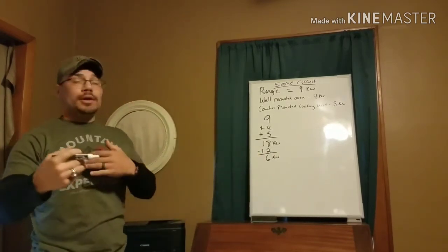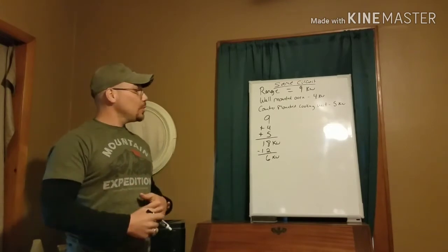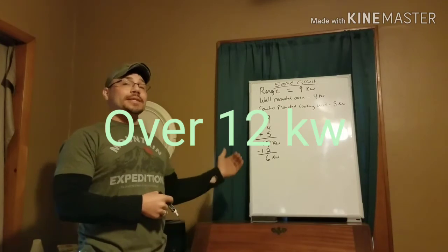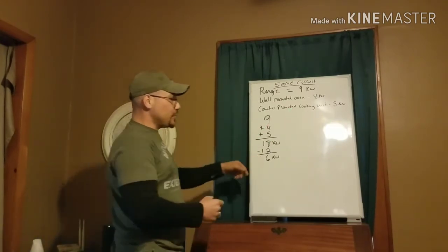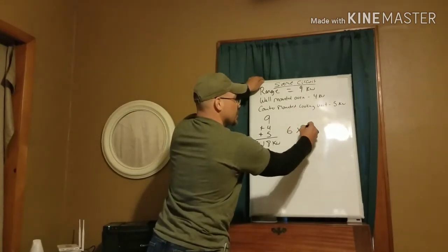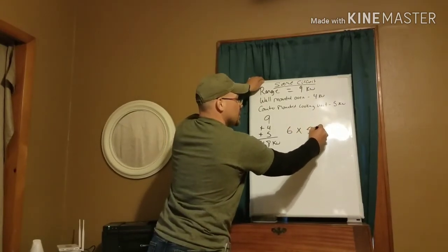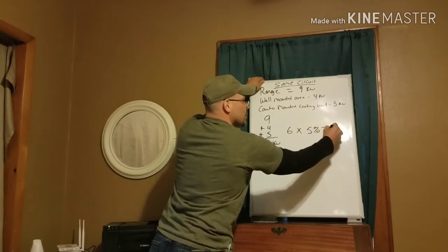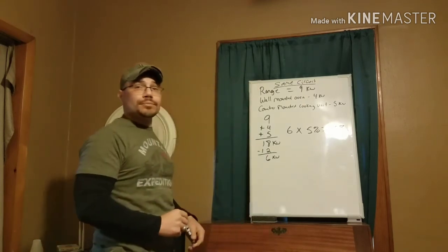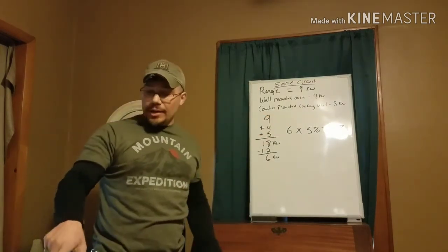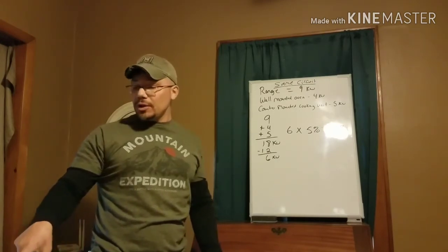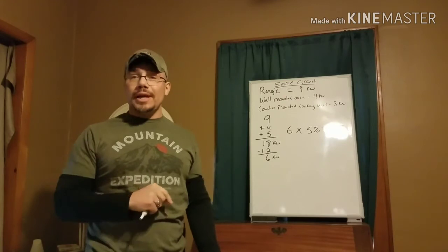Then it says for every 1,000 watts, or every major fraction thereof, we have to take that times our 5% again. So we have 6 1,000s. So 6 times 5% equals 30%. Right? Now, if you look at your number of appliances 1 on table 220.55, follow it across to column C, it says now our base is going to be 8 kilowatts.